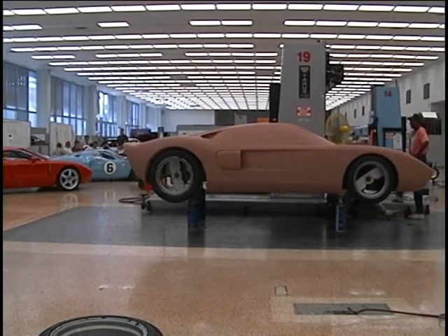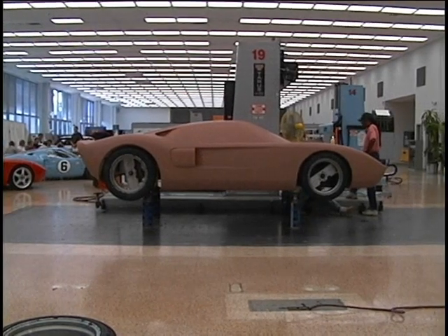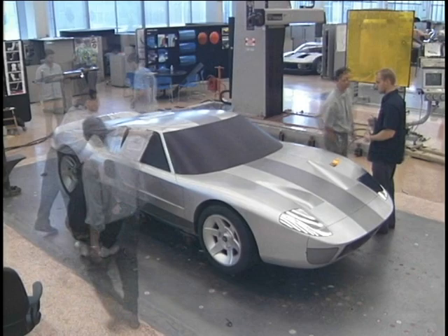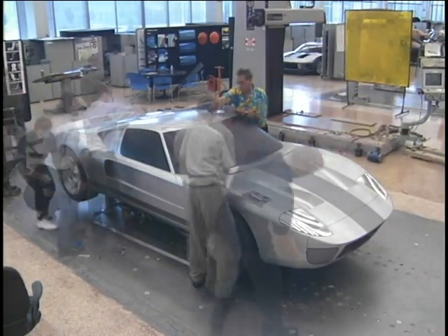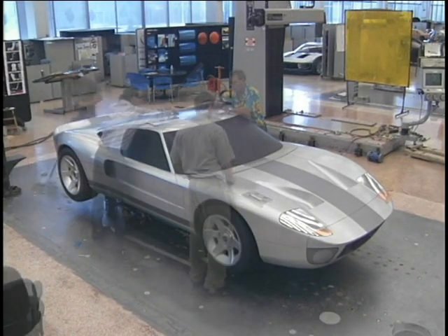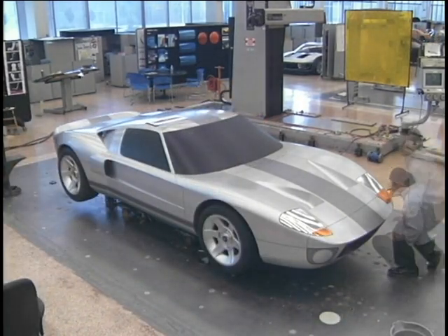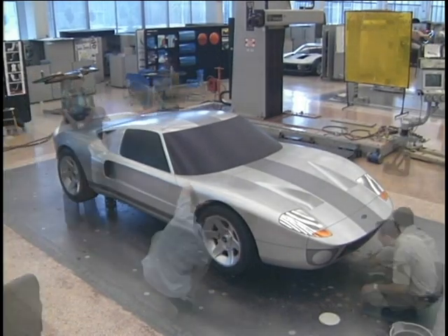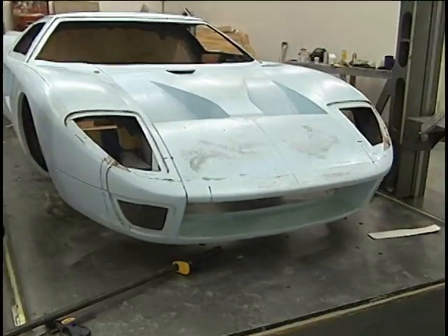After the design improvements to the clay model are completed, it is time to add color to the model. Most clay models are routinely covered in a silver-colored material called di-noc. This is a decal material consisting of 3 layers: a decal, glue, and paper. The silver di-noc is used for management reviews. The silver shows contours most effectively and is a neutral color for evaluation purposes.